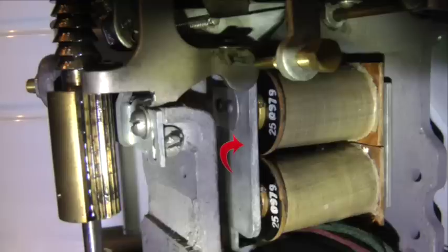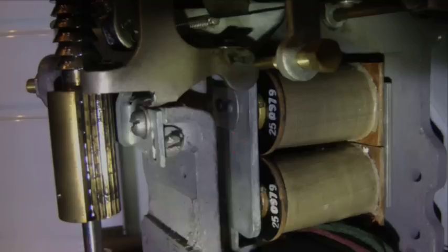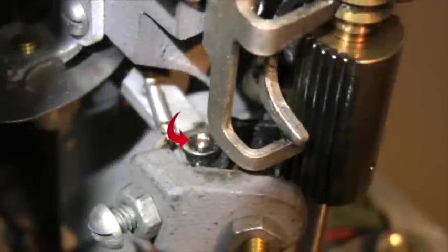It operates and releases repeatedly during the pulsing of the units digit in concert with the energizing and de-energizing of the rotary magnets. This is the rotary pawl, which is attached to the end of an arm on the rotary armature. Each time the rotary armature operates, the pawl engages a tooth in the rotary ratchet and rotates the shaft clockwise by 1 step.